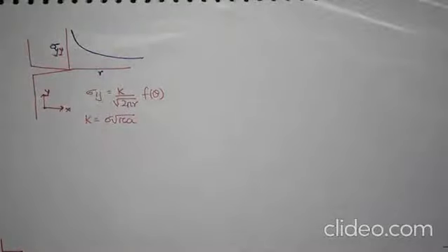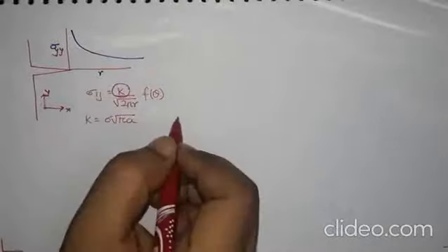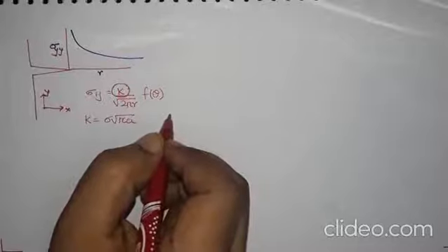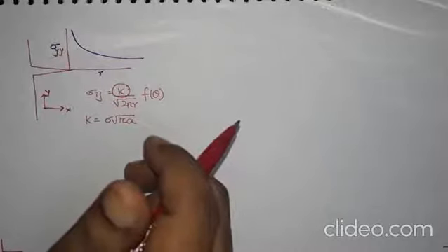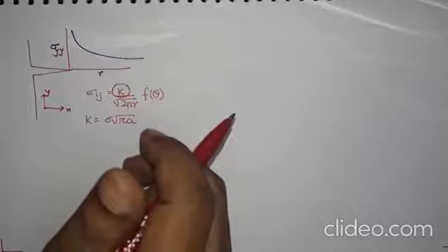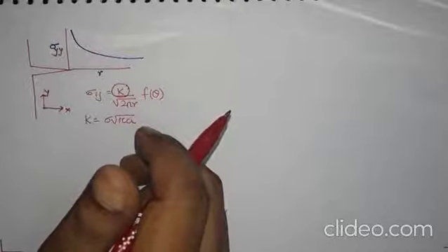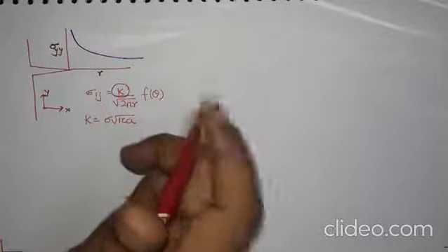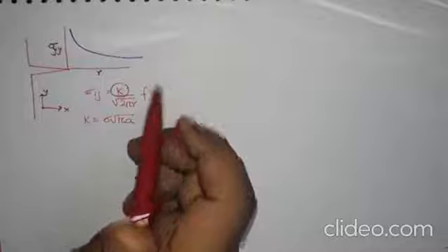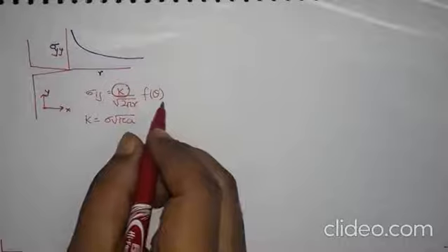So this parameter defines the intensification of the stress, and so it is called a stress intensity factor. And therefore this is a parameter which can describe a value which says how much this material is intensifying the stress, and therefore it could work as a fracture toughness value if it can provide you something which remains constant for a material. So there are material properties.